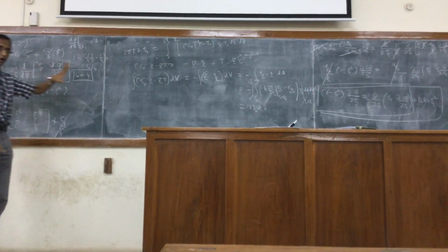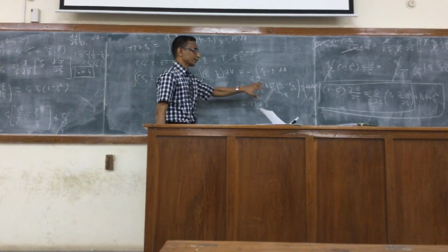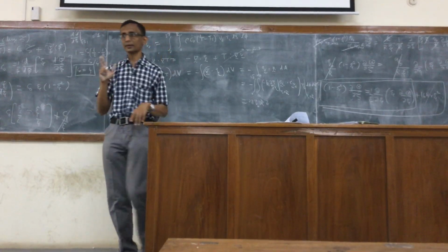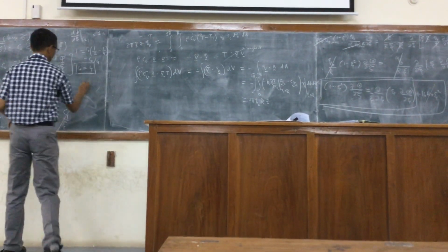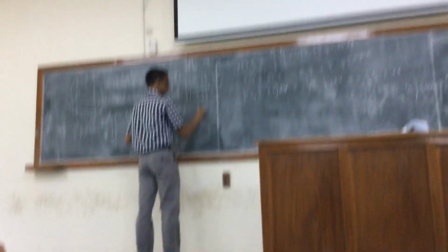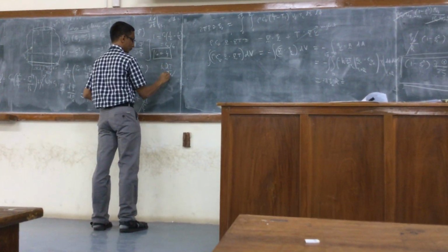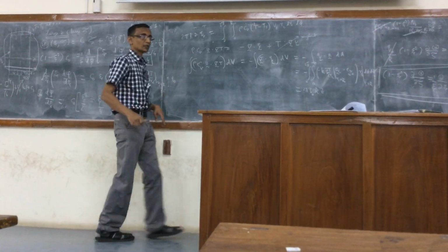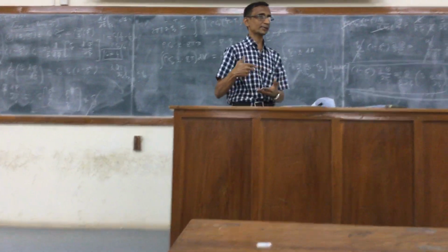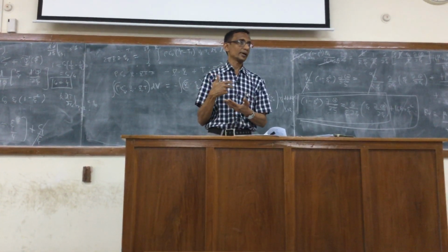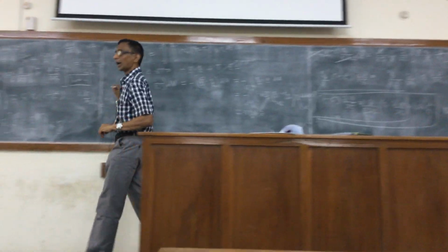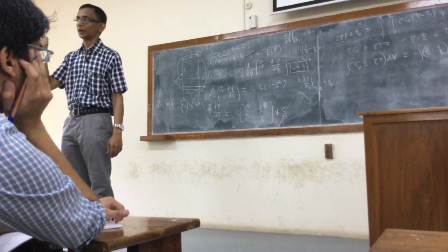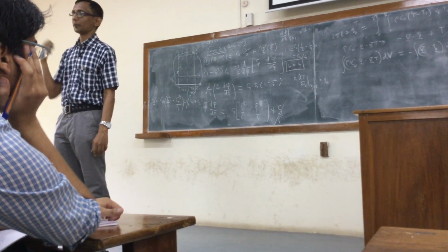You probably write it by inspection, integrated over the surface of the cylinder up to the point Z. If you do it formally, then you take care of the sign. You have to understand why the sign comes, for instance, why do we have K dT by dRC at RC equal to R equal to Q naught? This is a continuity of fluxes at the surface, right? Now Q naught has a sign. If Q naught is greater than 0, then heat is being provided from outside. It's being heated.